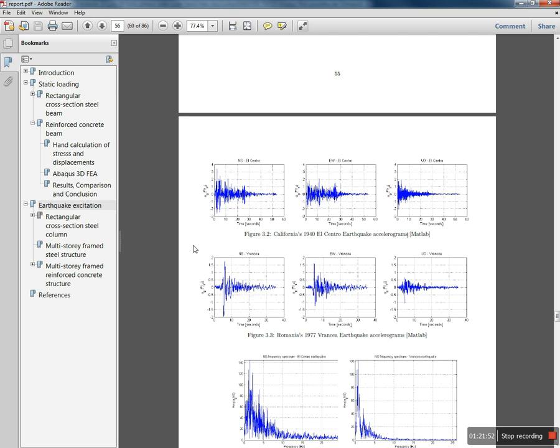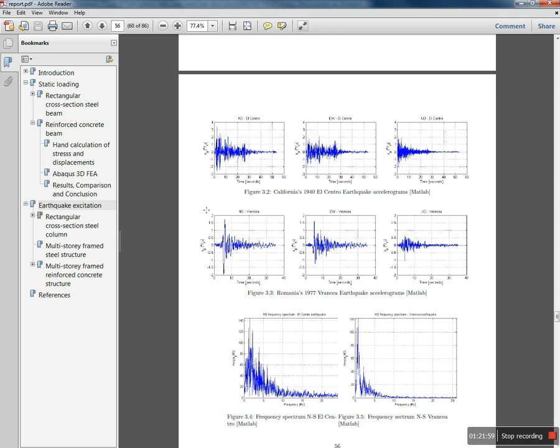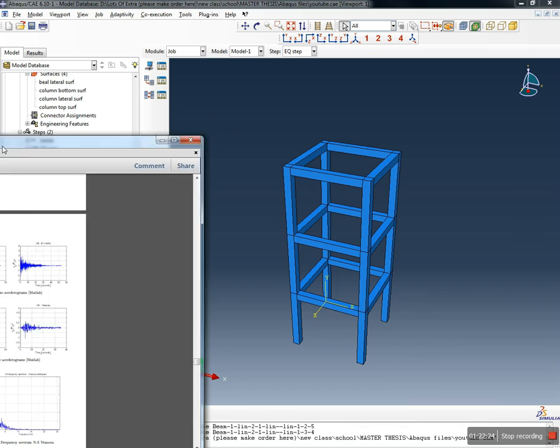And these accelerograms are public. Normally, you just have to find the station that was in charge at the moment with recording the accelerograms, and you just get them from their website, or simply Google them for the earthquake that you want. It shouldn't be a problem to get them. Yes. So you see, you can also have the east, west, and up, down, which is here for us. North, south is Z, and east, west we said is X, and up, down is Y.